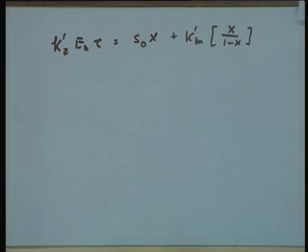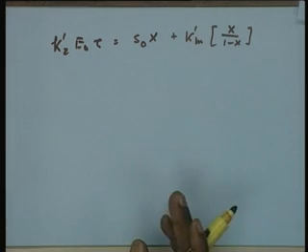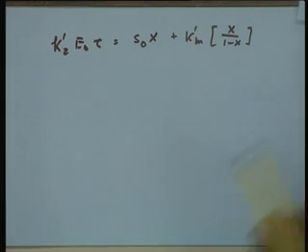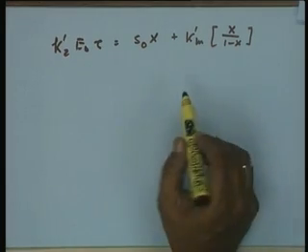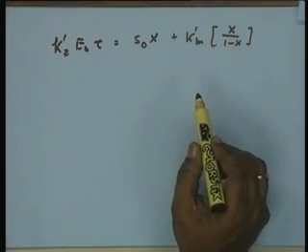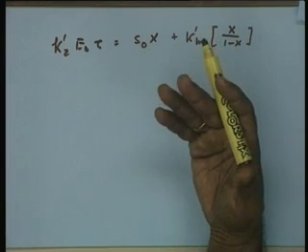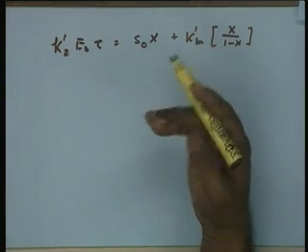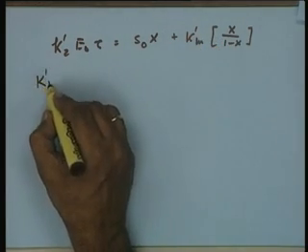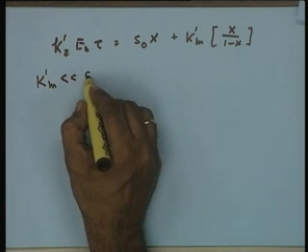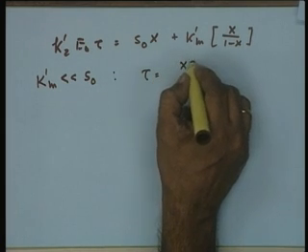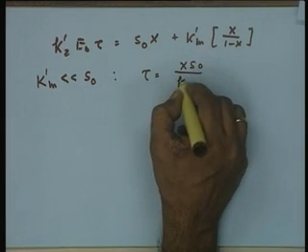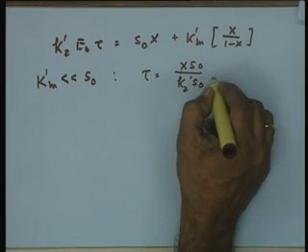That gives you the reactor performance for a CSTR, and if you again make a substitution for your x from the substrate concentration, you arrive at the reactor performance for CSTR. And similarly, here also you can make assumptions of 0 order or first order situation. When K dash m is much smaller than S naught, that is a 0 order system, tau is equal to x S naught upon K2 dash E naught.